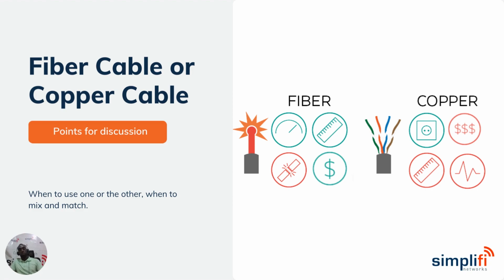Of course, that is not to say that fiber cable does not have issues. You typically need a little more to terminate fiber cable. It's a little more involved compared to the Ethernet. And also, repairing faults is not as straightforward as compared to just terminating an RJ45 of an Ethernet cable. So it's not a bed of roses with fiber, but definitely there are some strong points that we should consider.